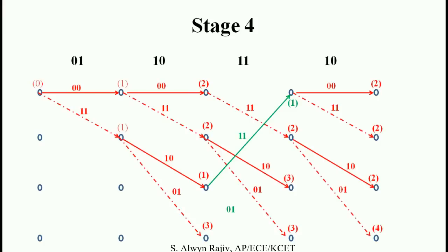Similarly, next is B to A. The input becomes 0, and the code word becomes 1 1. Only one bit needs to be changed, as mentioned on the green line, because each node receives two metric values on two paths. The Hamming distance is 1. 1 plus 3, the value becomes 4. Similarly, C to B, the value becomes 4.